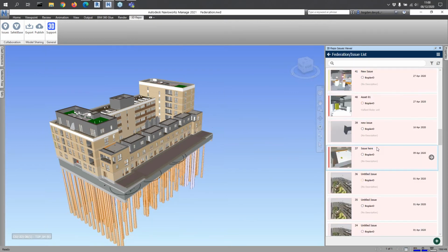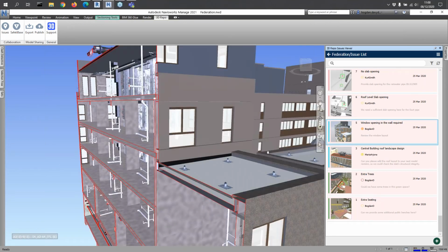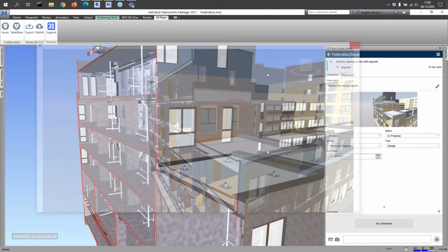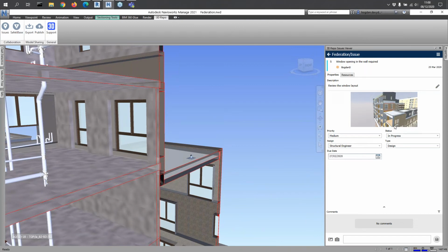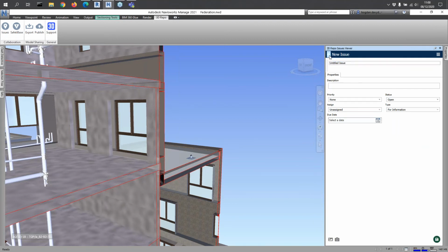And then from here, I can once again scroll through the list, maybe go to a particular model area, have a look what it is they're talking about, review its current status. Perhaps the opening is provided in here. It wasn't in the past. So this new model revision that I have federated has it. So I'm just going to close it off. I'm happy with it. Should I see any clash or an issue in Navisworks, once again, I can raise this directly in here as well.